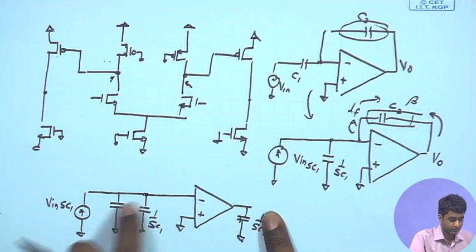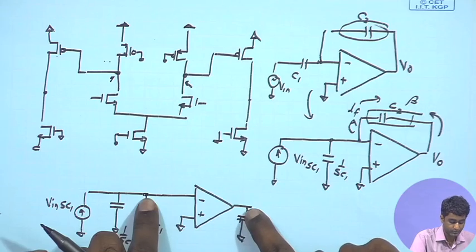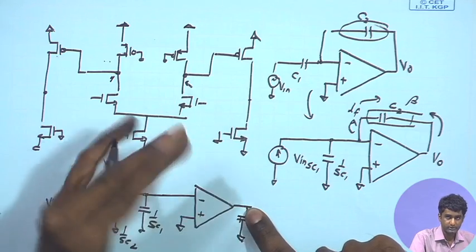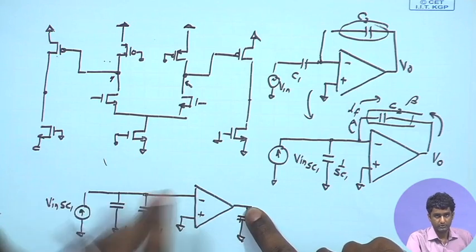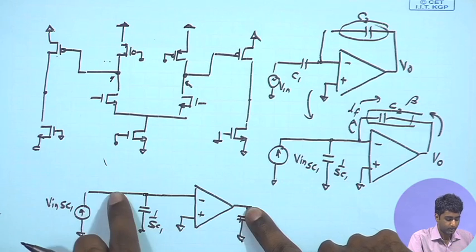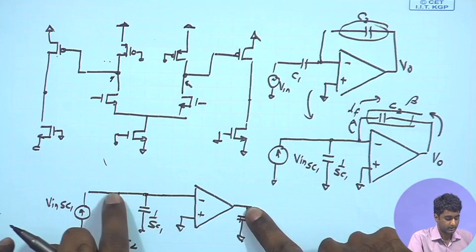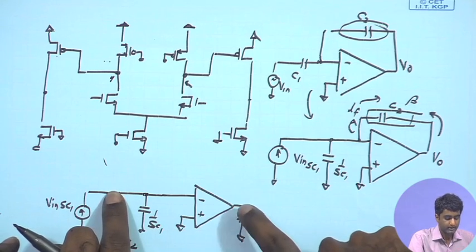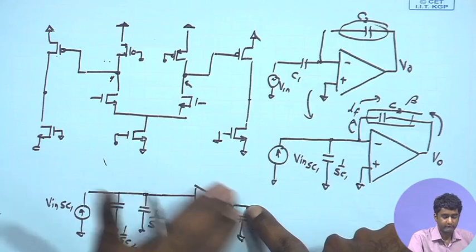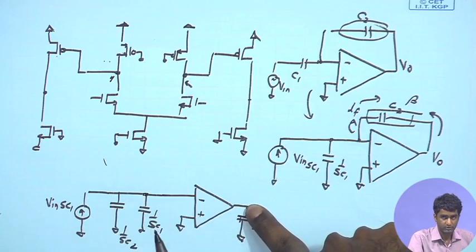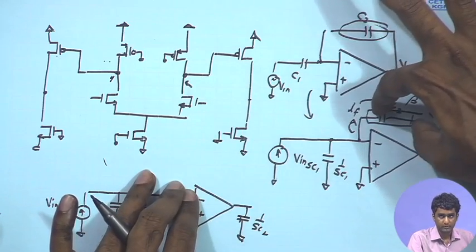For that, we first of all need to figure out the output voltage over here, and from there we need to find out what is the feedback current. That is the overall operation, right. So, the A, that is the open loop gain, basically the current to voltage gain, multiplied by the feedback factor, which is the voltage to current conversion factor obtained by this feedback network, that is known to us.